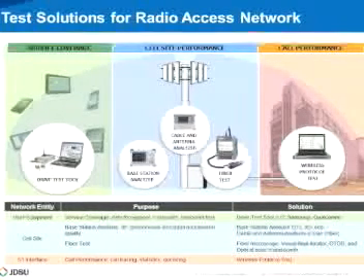And then ultimately onto the wireless protocol test. As a test engineer, I have a great deal of respect and admiration for centralized monitoring, trying to find as many faults with as few tests as well as test points as possible. So keep in mind that call performance, measuring it from protocol, is a great way of otherwise getting that first level of fault detection and knowing that there's a problem. So understand that there's a variety of tools and a variety of tests that can otherwise be deployed to otherwise characterize what's going on with your RF system.